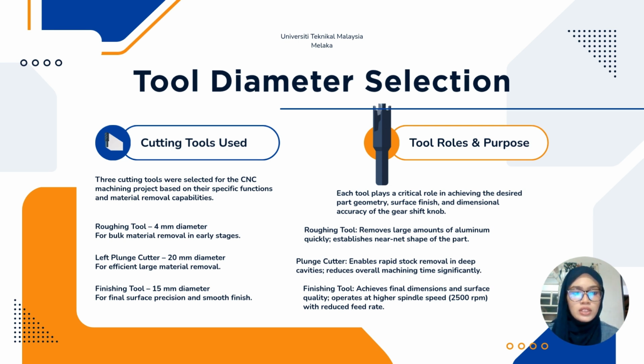Next, the 20mm left plunge cutter quickly removed material from deeper areas, helping reduce machining time. Finally, the 15mm finishing tool is used to achieve the final dimensions and a smooth surface finish. It operates at a higher spindle speed of 2500 rpm with a lower feed rate for better accuracy. Using the right tool for each stage improves machining efficiency, accuracy, and surface quality.